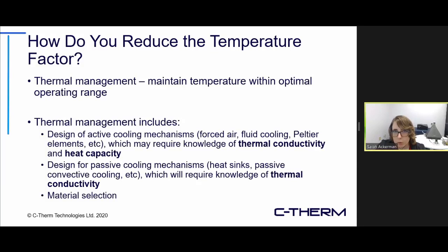A third component to thermal management that is becoming more widely used is material selection. So basically choosing your materials of construction with thermal management in mind, whereas before the thermal properties of the material might have been secondary, where you would look at them in your design after you chose the materials.